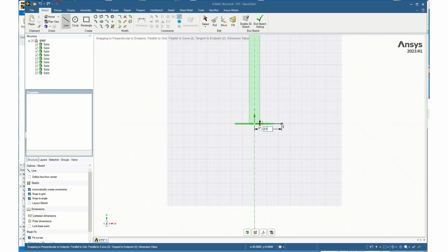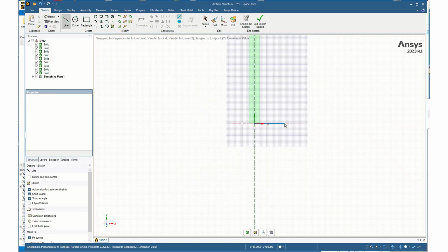to be 51 millimeters. So I type in 51, enter. Now I can click and move this down, and I move it down 7.1 millimeters. And there's that line. Click it, move in, and I'm going to move in 48.1, enter, millimeters. And I just keep outlining my geometry like this. Now I can move this one down 138.8 millimeters, and hit enter, and that gives me the line there.